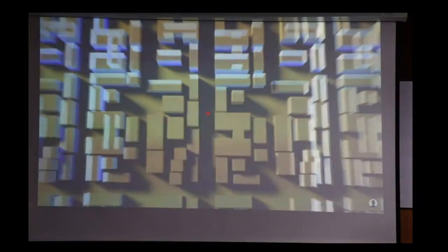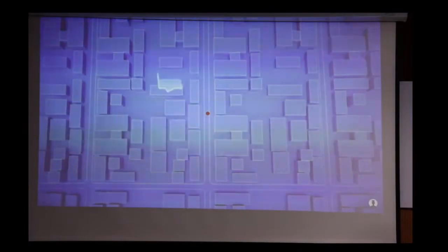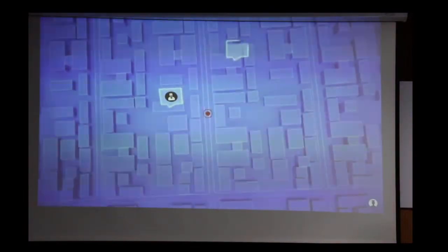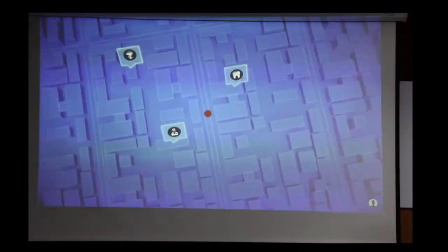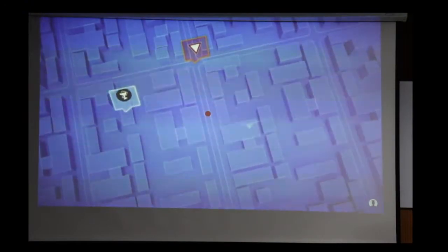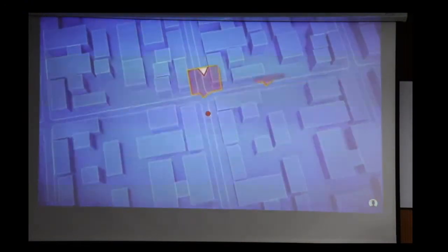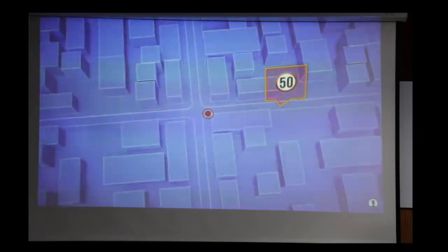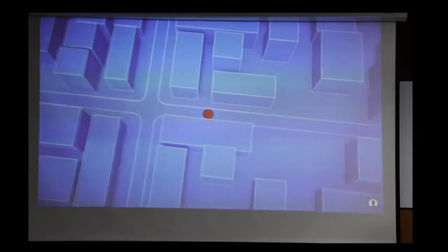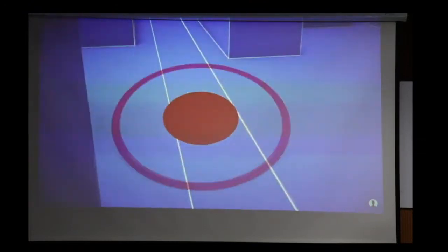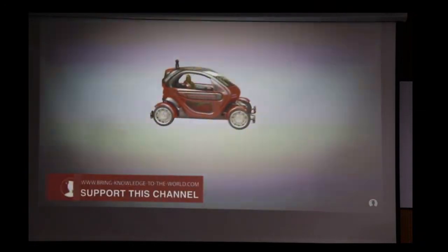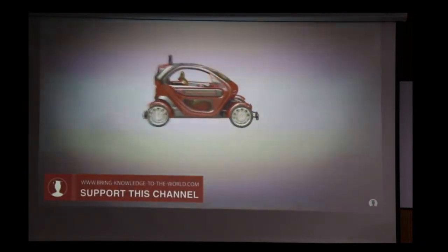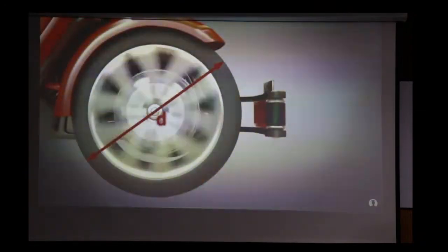The exact position of the vehicle is determined by GPS and highly accurate digital maps. Digital maps contain a lot of information, including information such as intersection signs and speed limits. Since GPS cannot always be guaranteed, for example in tunnels and street canyons, odometry is also necessary. For example, the wheel diameter and the wheel speed can be used to estimate the future position of the vehicle.